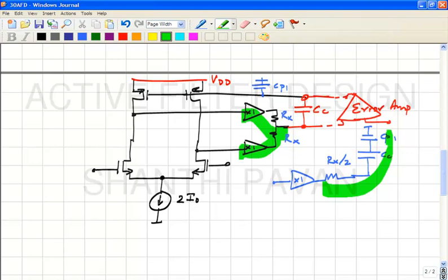So this introduces an extra pole in the feedback loop, or more delay. So what comment can you make about the inductance that you see? Yeah, so what this is telling you is that this is no longer behaving like a pure resistor, right? This also behaves like an inductor because of the delay associated with the RC network. Because if you yank the common mode at the input of the buffer, the output is not changing instantaneously, which is what would be required in order to realize a resistor. Is that clear? So what do you think? Can you think of a fix for this?